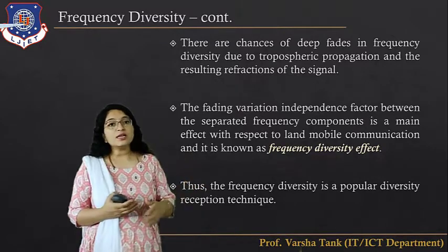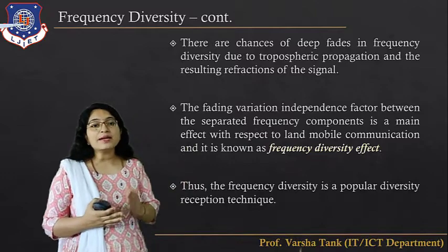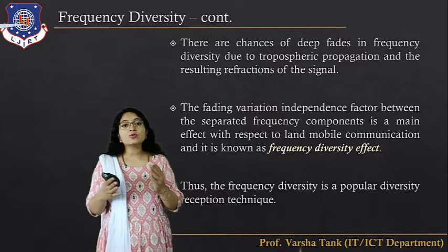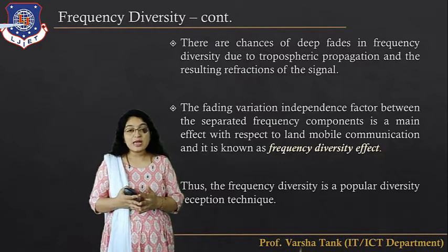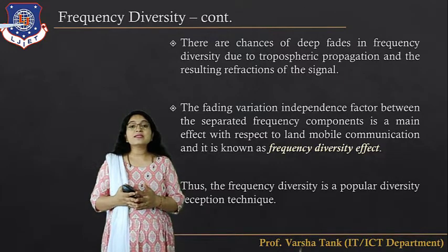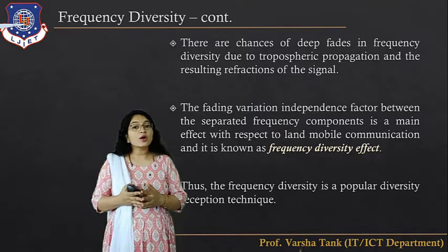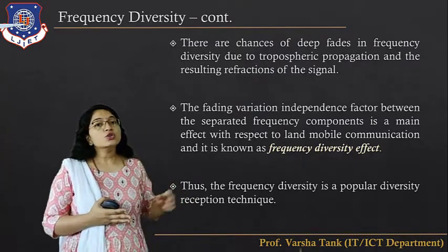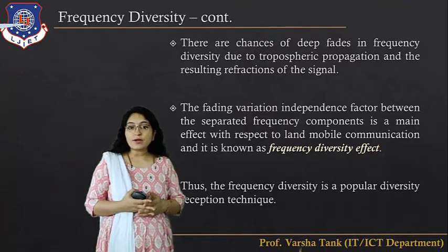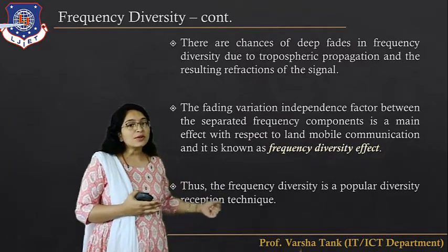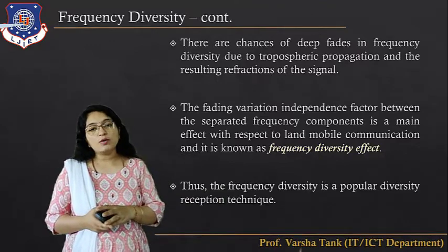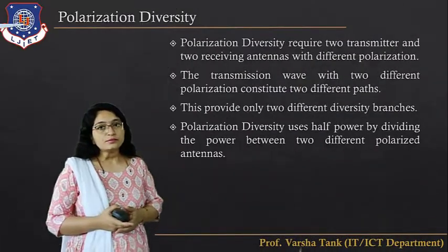The fading variation independence between the separated frequency components is the main effect with respect to land mobile communication, and this is known as the frequency diversity effect. Thus, frequency diversity is a popular diversity reception technique among all the techniques.